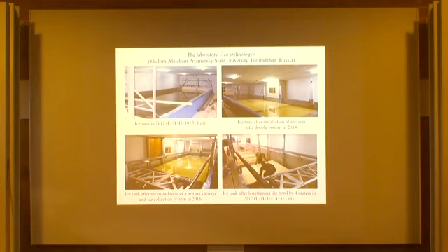The ice tank is equipped with systems for collecting and melting model ice. After the test, the broken ice pieces left in the ice tank are removed into special tanks, which are metal containers covered by a layer of insulation with electric heating elements.